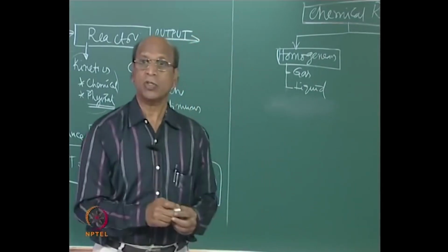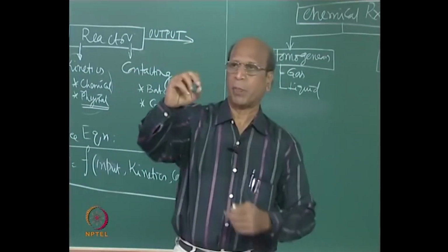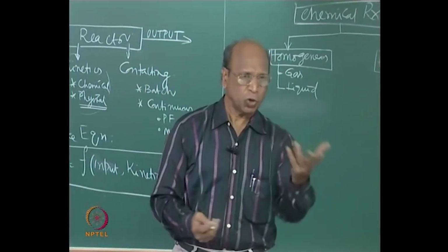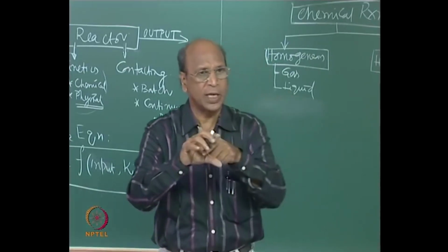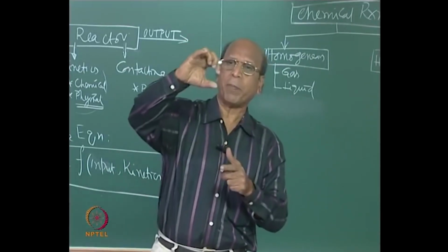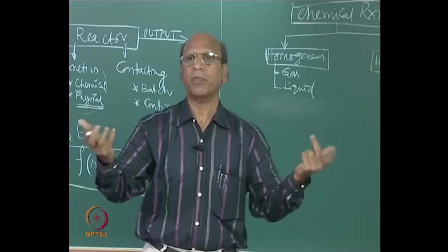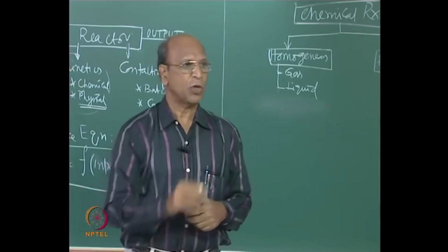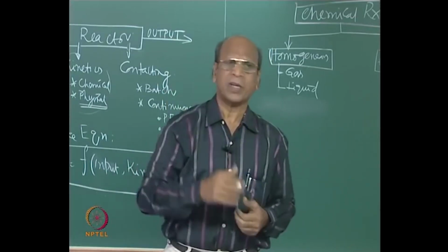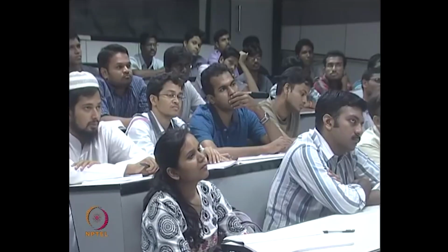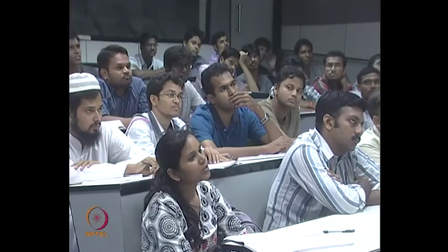So, that is the reason, and also as the diameter of the particle is increasing, we talked about the mass transfer step: the gas has to diffuse into the particle. If you have a bigger particle, then the diffusion is not very fast. When you have a small particle, diffusion is very fast. That means, you have heard of effectiveness factors, right? Big particle, diffusion is difficult.